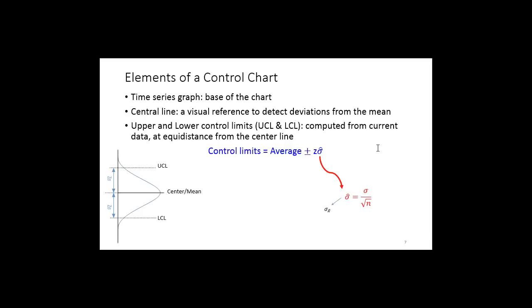The expected value of the sample mean is a number we expect to be the mean of the population. When making a control chart, we have basic elements. The first element is a central line, and that central line is the average of all samples, or a target value we expect the samples to follow. There are two limits, upper and lower. Upper control limit and lower control limit.